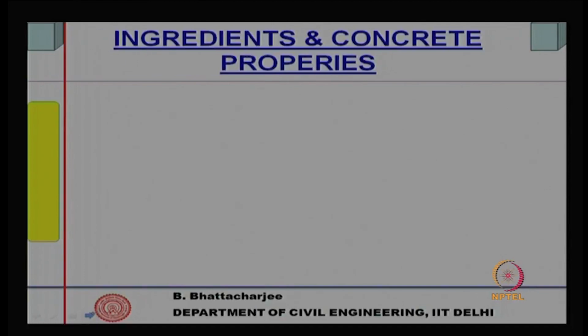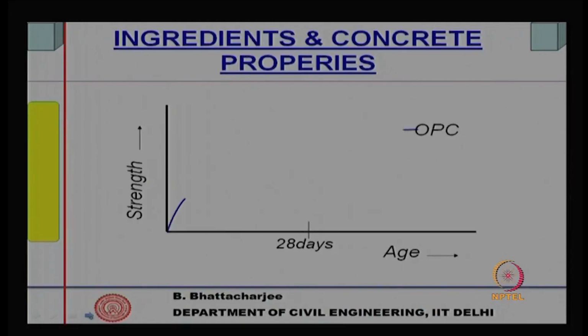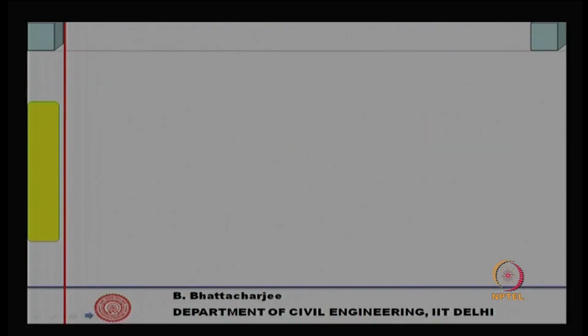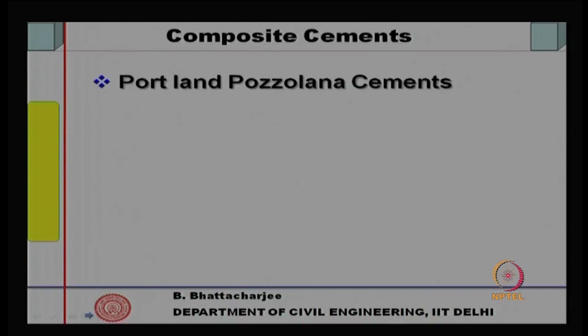So, blended cements are produced from this. One important issue is that such cements, when you produce them by intergrinding gypsum, clinker and the pozzolana, have lower initial strength, but long term strength is better, particularly with fly ash. And so is the case with slag, but silica fume can show you high early strength as well. We will discuss this sometime later on.